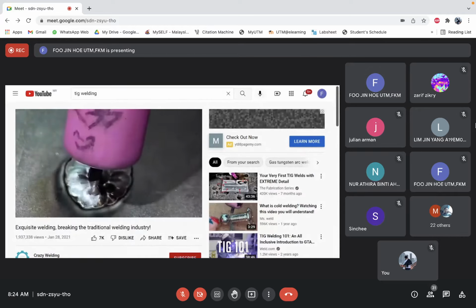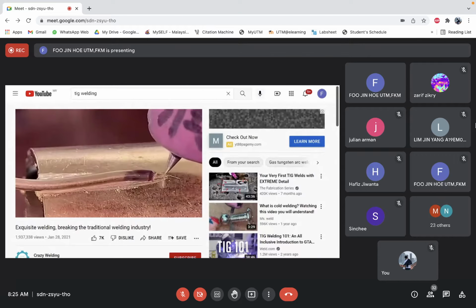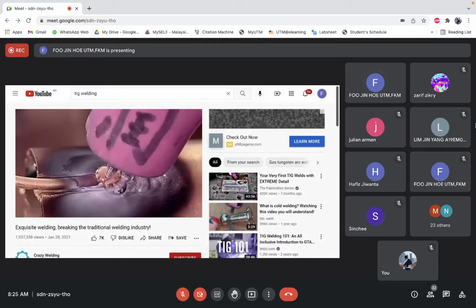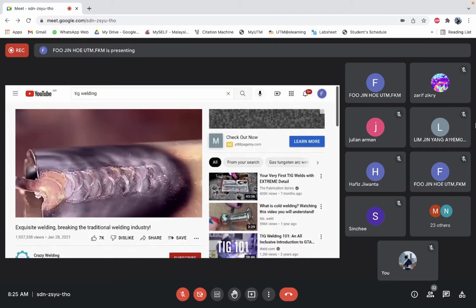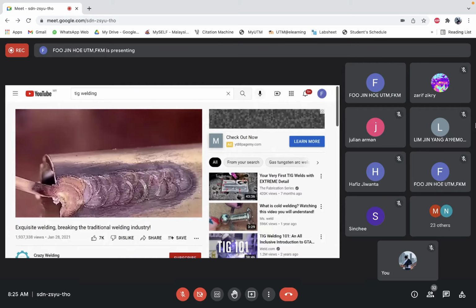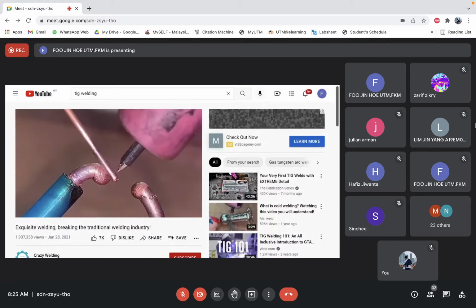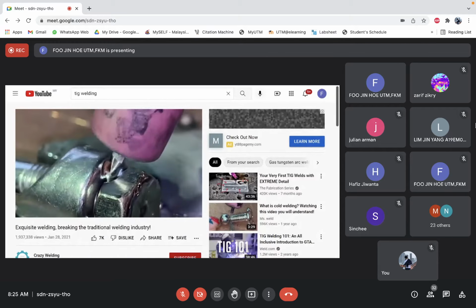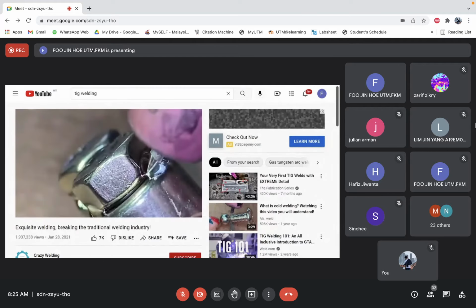For the weld metal of heat-resistant low alloy steel and high alloy steel, the chemical composition or corrosion resistance should be guaranteed under the premise of ensuring the mechanical properties. The actual meaning of guarantee is chemical composition for chromium molybdenum steel, but for high alloy steel, the corrosion resistance should be higher than or equal to the lower limit of the value specified in the corresponding base metal standard or meet the technical requirements specified in the drawing.